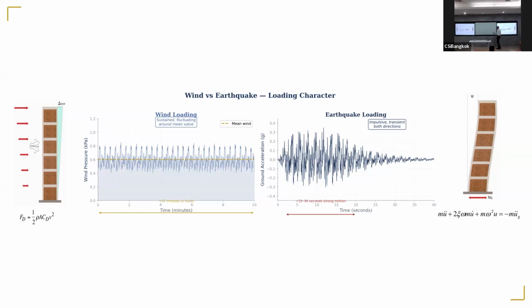So now these days, the tendency is that just like earthquake, where you have seismic time history simulation analysis, we also have the wind PBD, in which you take the wind pressure in a wind tunnel, and then you measure the pressure at every location on the building with a pressure tap, and then you get the time history of the wind, and then you apply those time histories of the wind onto the structure as a time varying force.